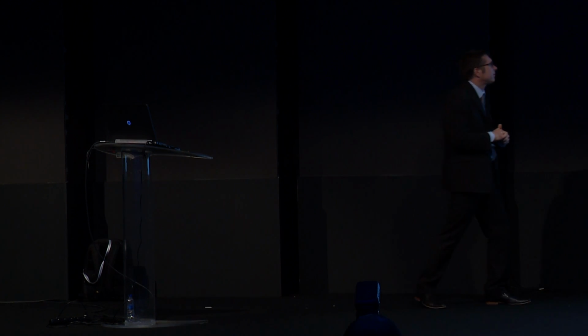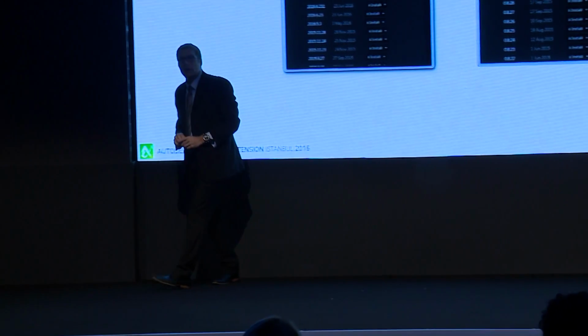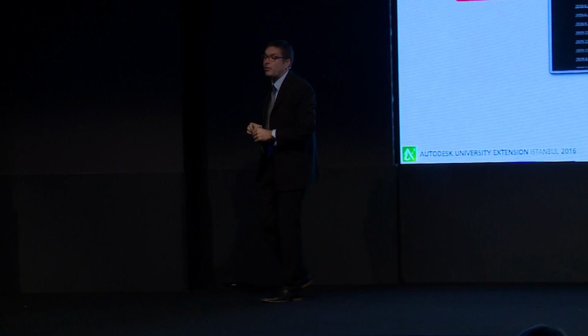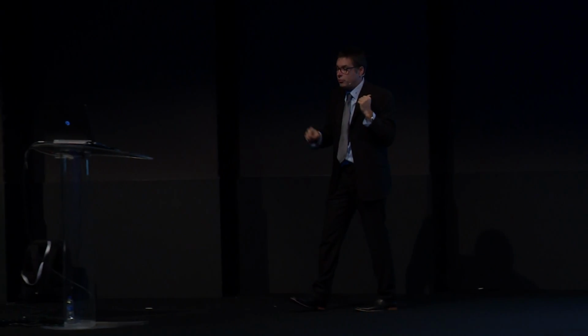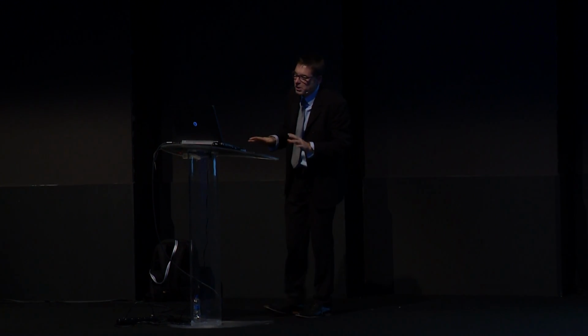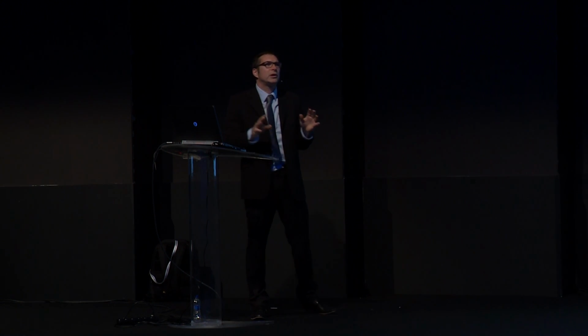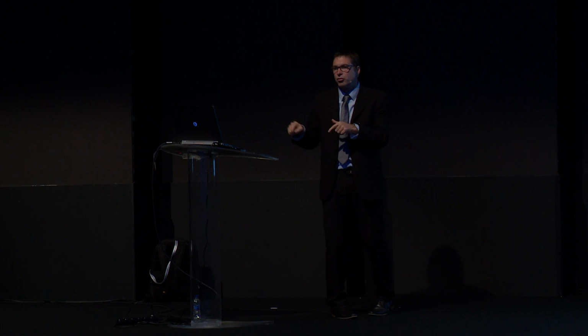And another advice, as you see, it is a package here. It's a Dynamo package. Today, it is released only for the previous version. That means if you want to use this in the current version, the 17 version, it can't run. So be careful. You need to install the previous and the new version. To be honest, actually, I use the previous version more frequently than the recent version, because packages are not all updated.